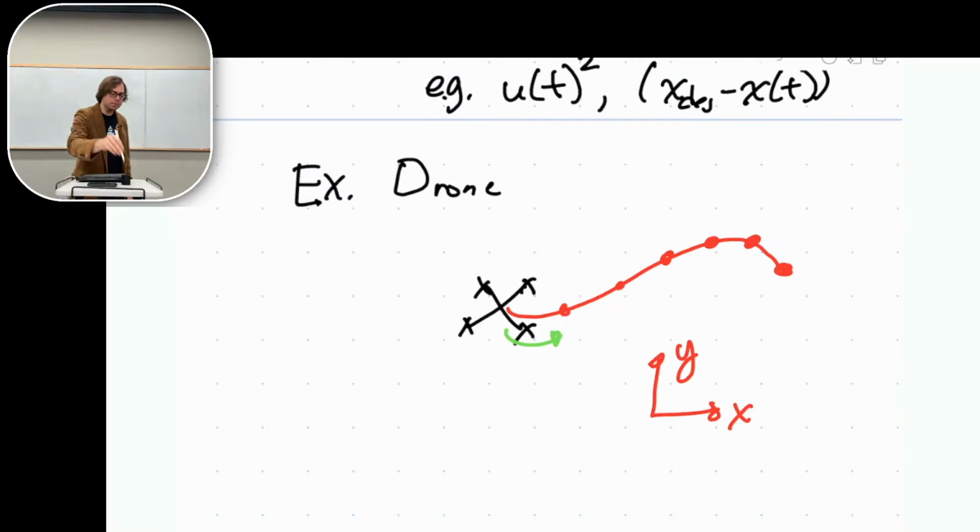Anyone's seen, I think up until the last 18 months, those Boston Dynamics humanoid robots that jump around and do parkour? I know I've shown them a couple times. They use model predictive control. Very nonlinear dynamics. What they are doing is they're constantly relinearizing. They say, okay, I have a linearization. It's going to be good for just this right here and now. It's only going to be good for this very narrow region. I'm going to make a prediction into the future. Then I'm going to be in this pose in the future. I'm going to relinearize about that pose. And it's doing that over and over and over again.